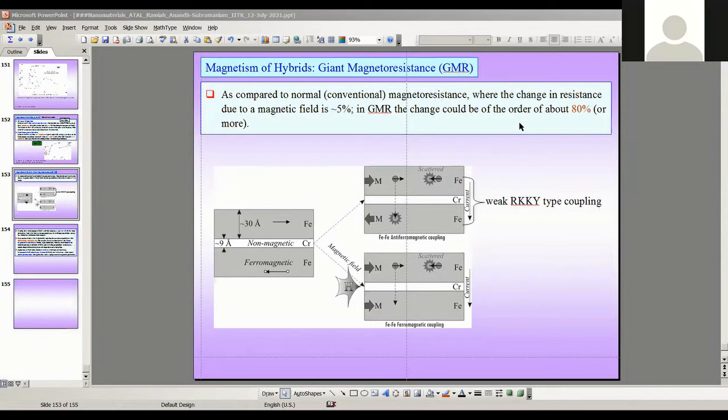I've talked to experts like, for instance, Professor Mahajan, originally at Carnegie Mellon University, who has written a very tough volume on deformation twinning, a difficult book to read. Now they believe that the dislocation pileup mechanism may not be a good enough explanation for the Hall-Petch effect. Whatever it is, it's an experimental observation.